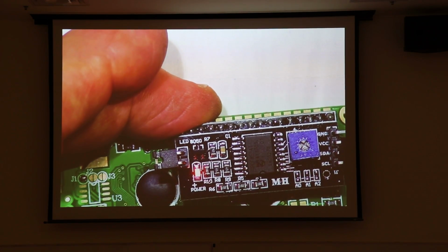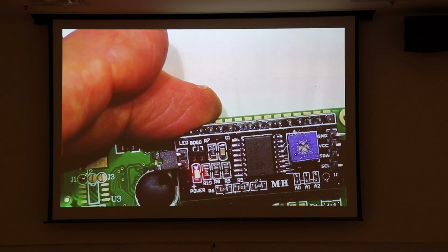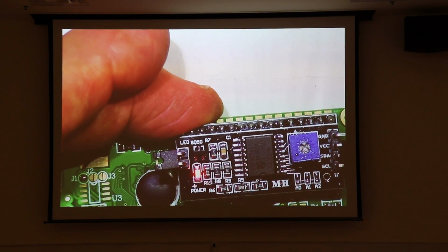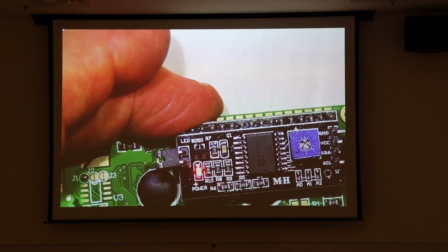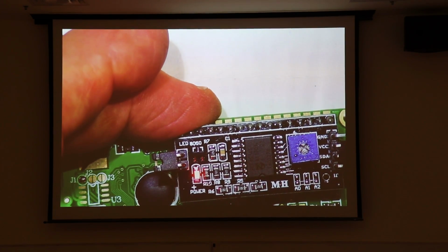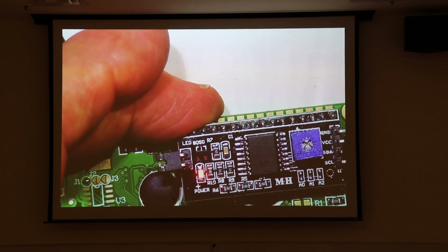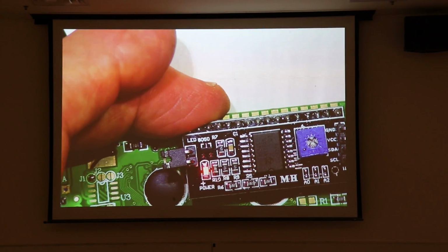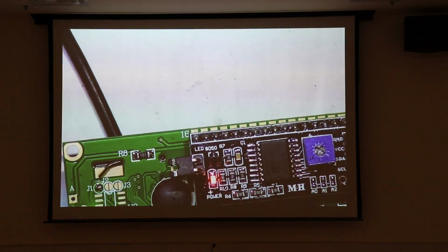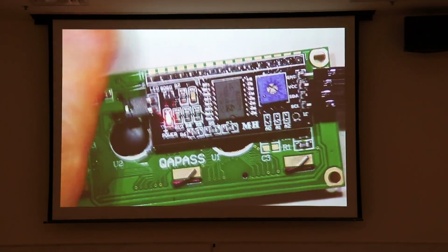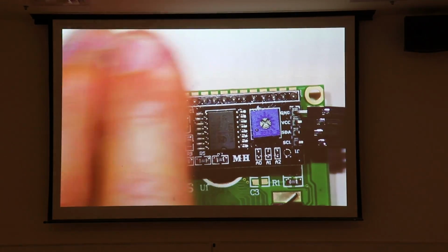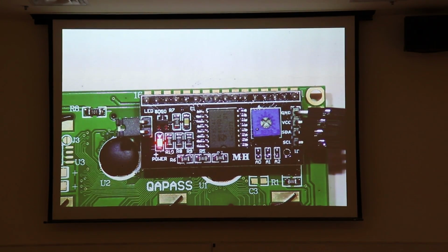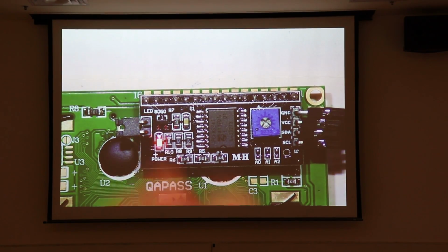It connects to the PCF 8574 and sets the 3 bits of address that you're allowed to set externally. So the chip is hardwired from this chip 20 slave address hex to 27. But those last 3 bits can be set, and that's how you can pick it from 20 to 27. So you can have it be 20, 21, 22, 23, 24, 25, 26, and 27. And that's nice because it lets you have multiple chips. The problem with it is that unless you know how these are actually set, you may not be sure what slave number to give your device when you're trying to talk to it, and it can drive you a little crazy to begin with.